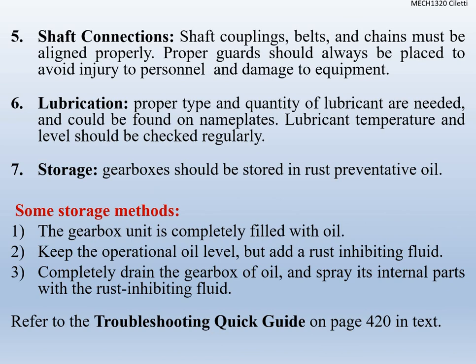We're going to use shaft connections, couplings, belts, chain drives, and all of those have to be properly aligned. We're going to go through different labs in class to make sure everything is aligned correctly, and we're going to have all of our different guards in place for that as well. Everything needs to be lubricated. So even in our lab, we're going to use some dry lubricant or different types of lubricant. We're going to grease our bearings and that sort of thing as we use these.